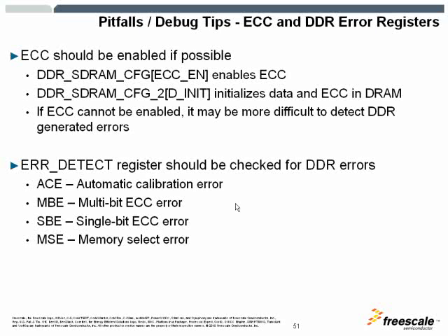Next, we're going to talk about ECC. This is the single most important part of DDR subsystems. It doesn't matter if you're using our parts or some other parts, ECC is very important in debugging any failures that happen in DRAMs, so do provide ECC in your system as a good feature.